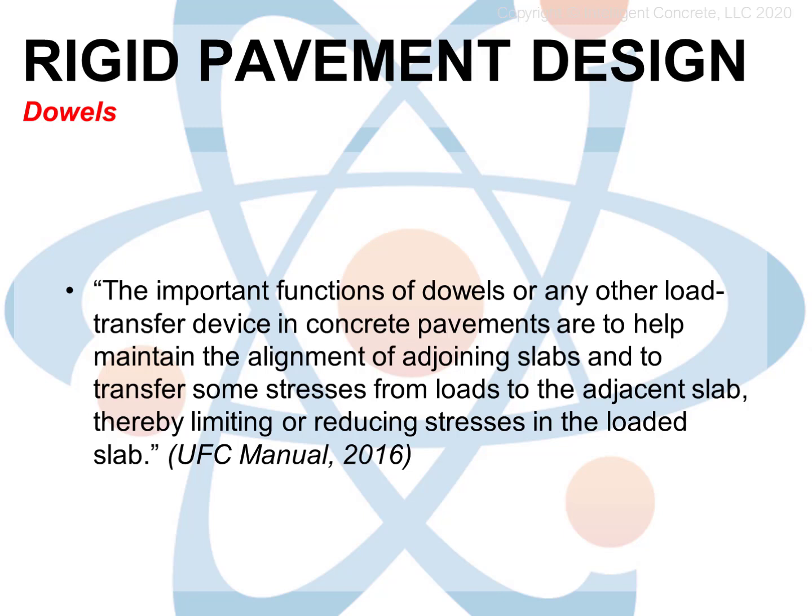This load transfer from one slab section to the next functions really as an impact load. Very small at first, but think about all the times it has to happen. On a freeway with millions of vehicles, it's a constant process. On an airfield, there will be fewer vehicles, but they are typically much heavier.